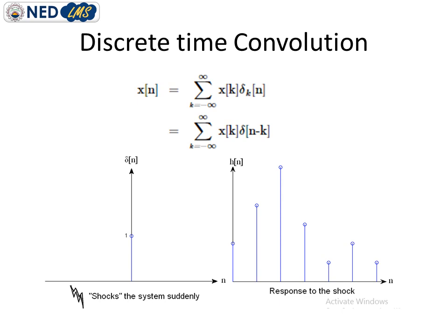If you see the plot, the first plot is for the delta function denoted by delta of n. This function is a normalized impulse, which means that sample number 0 has a value of 1 and all other samples have a value of 0. Because of this very reason, this delta function is termed the unit impulse function.